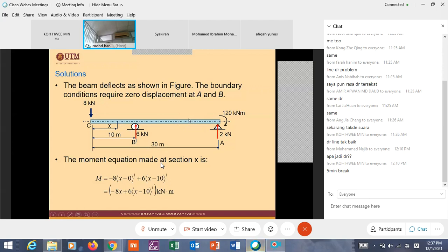Remember, the principle is that you use the point X for the derivation of bending moment, where X has passed all the loading to the left. Derive moment at point X where X has passed all the loading at left.